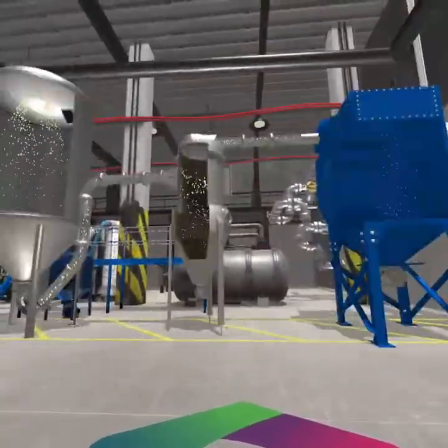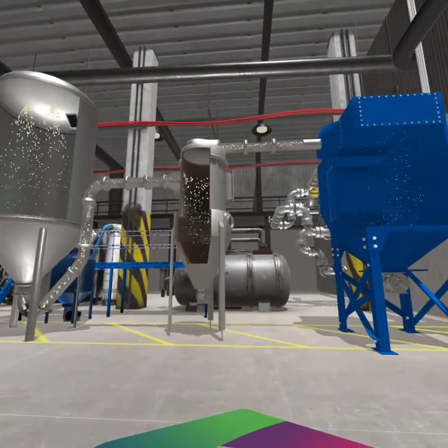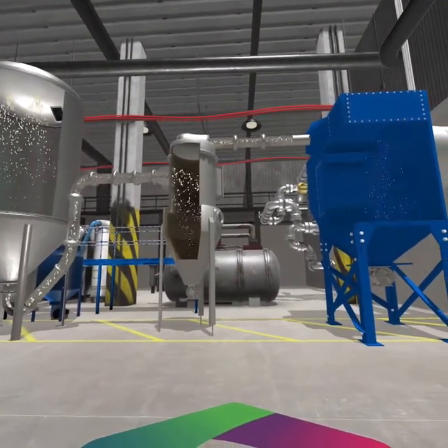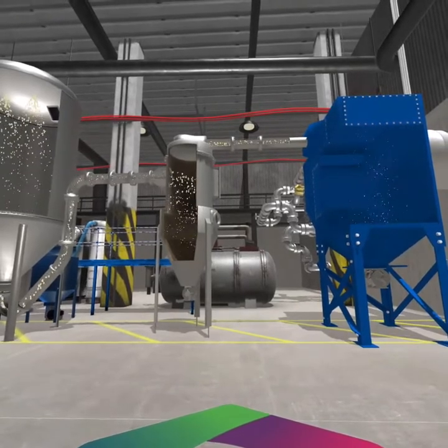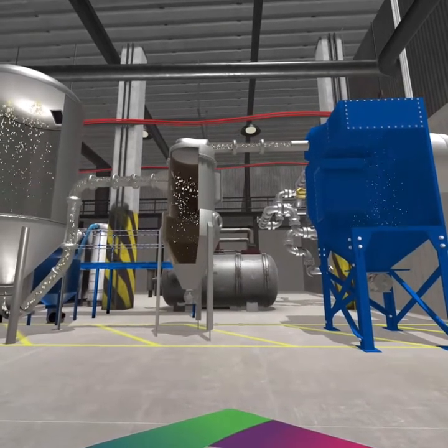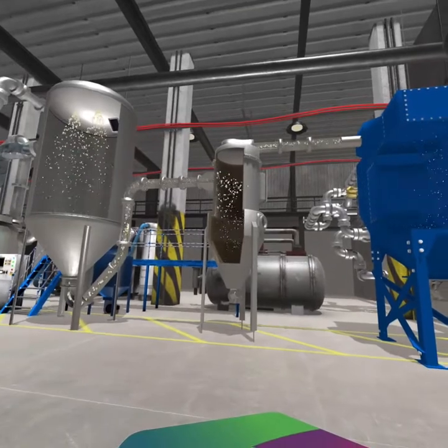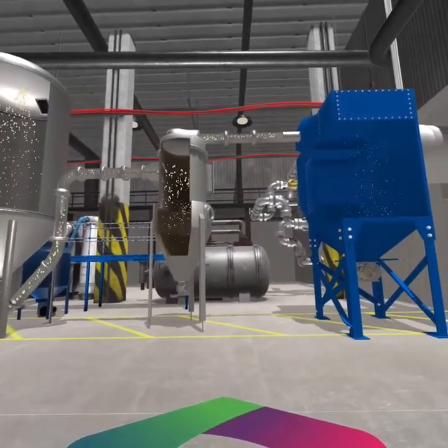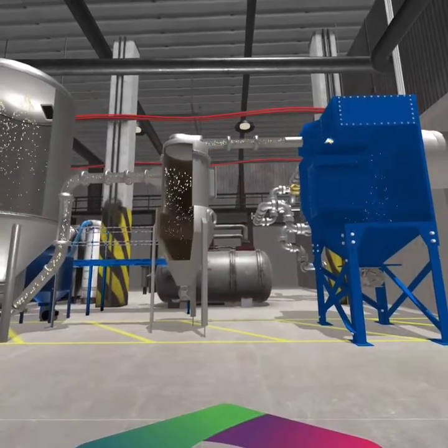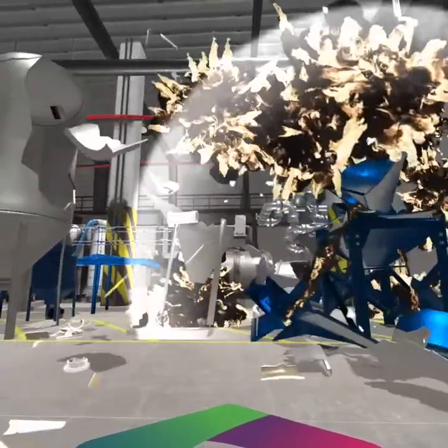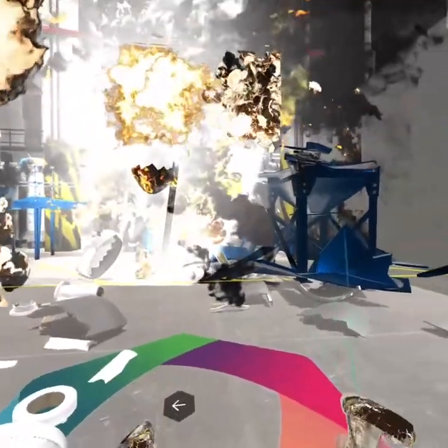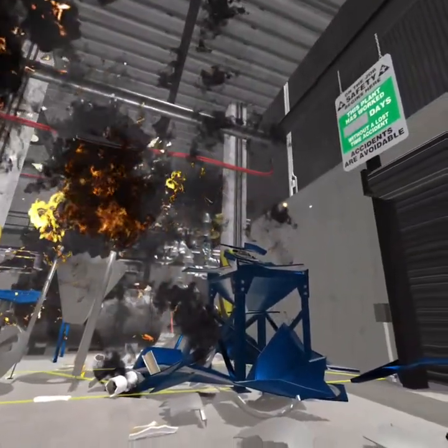The process appeared to be operating normally, but every ingredient required for a dust explosion was present. First, we had fine, dry dust. When this fuel was combined with oxygen and dispersed in a confined vessel, all that was needed was an ignition source, and in this case, an upset condition in the form of an exothermic reaction from material built up in the spray dryer created the ember that triggered the explosion.